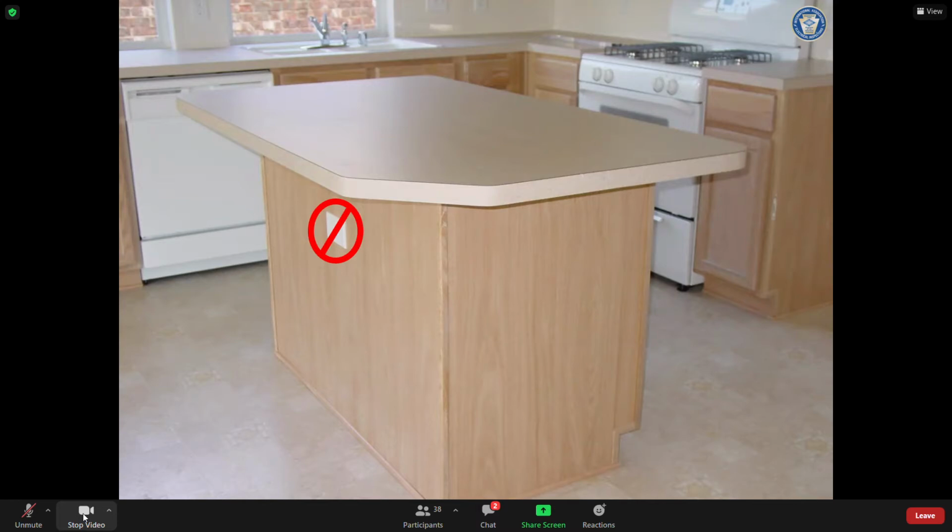Now, if I were the AHJ, guess what? I would try to make them get rid of that receptacle because Francisco said it correctly. If you leave it there, guess what? They're going to use it. Yeah, they are going to use it. And this one's under an overhang of greater than 6 inches, whereas the one we looked at was not under an overhang of greater than 6 inches. So you're actually posing a hazard here with that exposed cord. Yep.